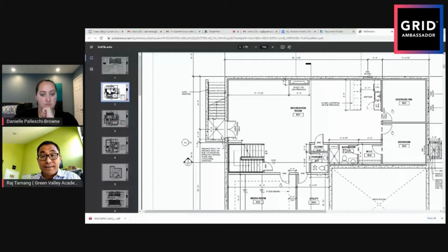What are the setbacks, right? How much you have to leave from the front, on the side, or back. That also depends on zoning. It's R1, R2, R3, different zoning categories where the requirements are different. All that is shown on the grading plan.